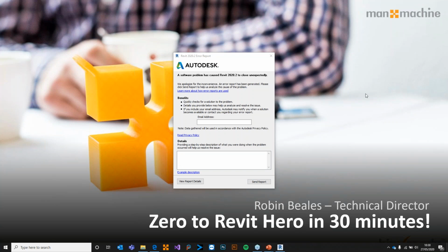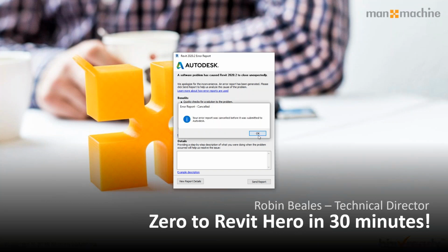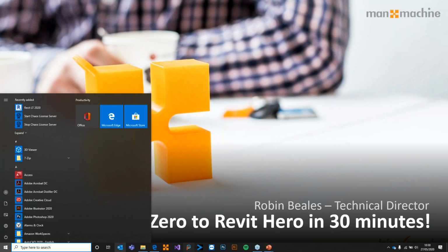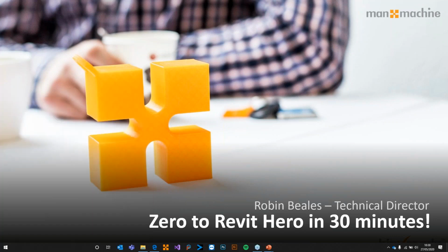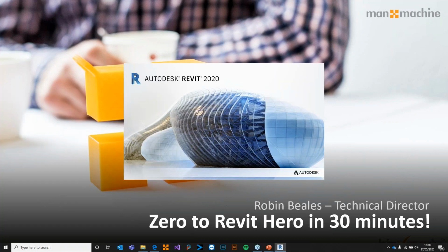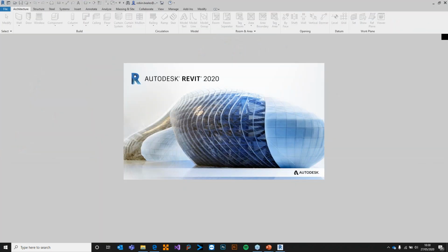Okay, so I didn't manage to show you the finished result, and I didn't save the model. So rule number 1, make sure you save the model before you start a third-party plugin in case it crashes like that did. Rule number 2, Revit doesn't auto-save, so make sure you save the model before you start a render. But actually, hopefully that's been useful. It's kind of all I wanted to show. I just hoped to show you a pretty render at the end there.